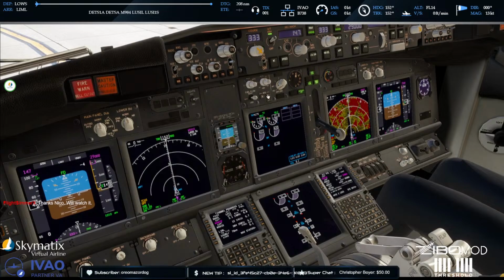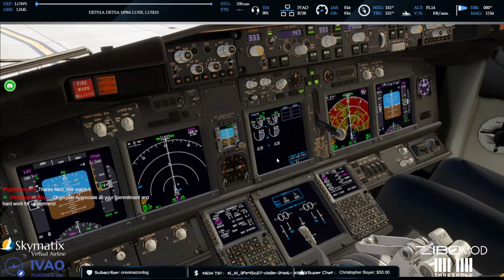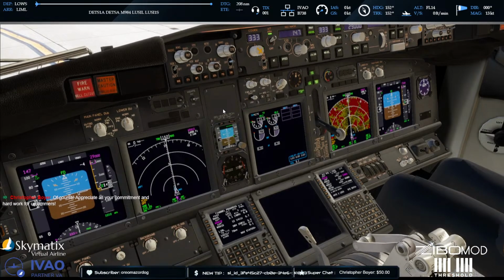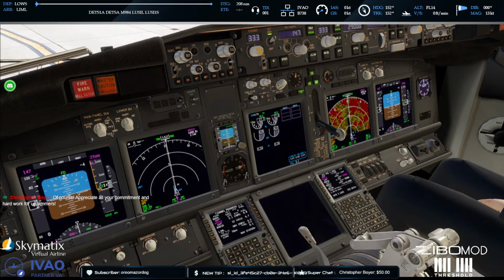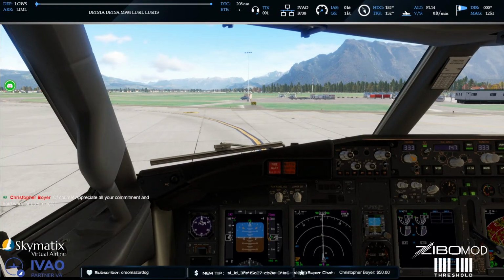Okay, so next. The only thing that video doesn't do correctly as per normal SOPs is he allows the start cycle to go to max N2 before he opens the fuel cock. Normally it's opened at 25%.